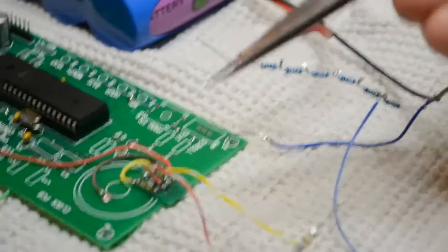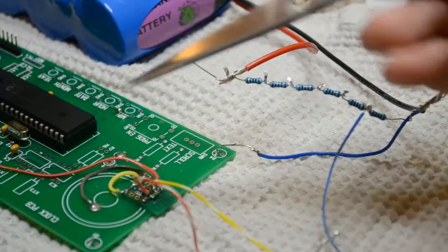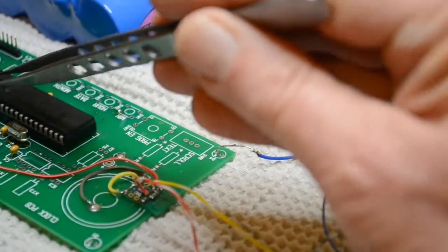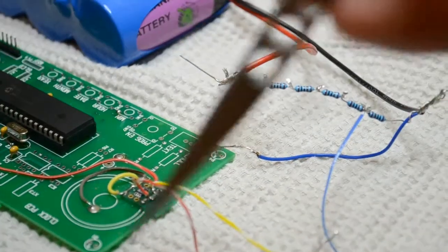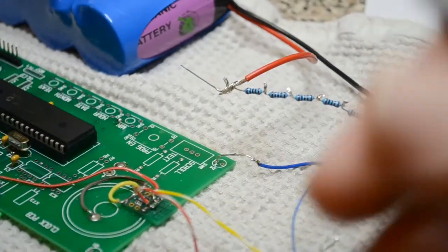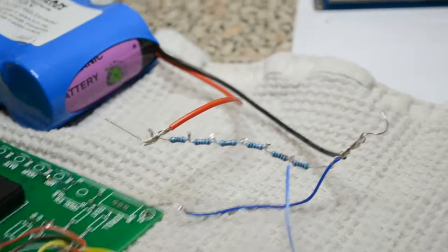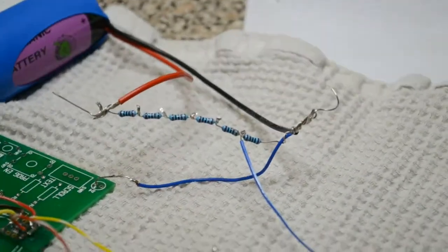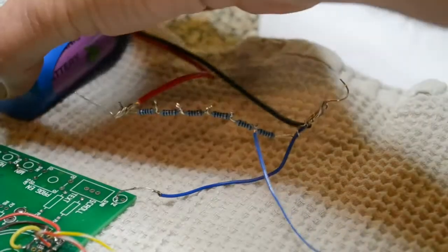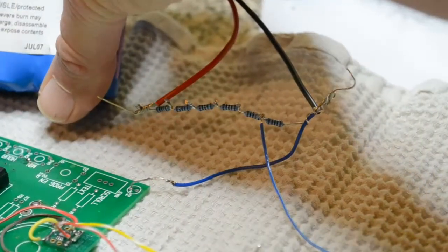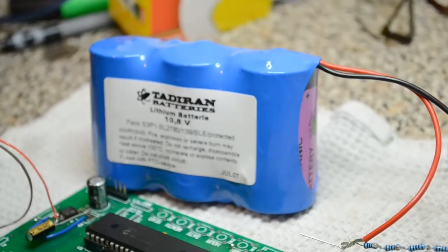Right, so I've got my analog devices current to voltage converter going in on one analog to digital pin, AN0, and I've got this blue wire here going into AN1, so the second analog to digital converter channel. Now that is running to this voltage divider, and you might see, so I've got this 10.8 volt lithium battery in the corner to simulate a higher voltage running into the PIC.